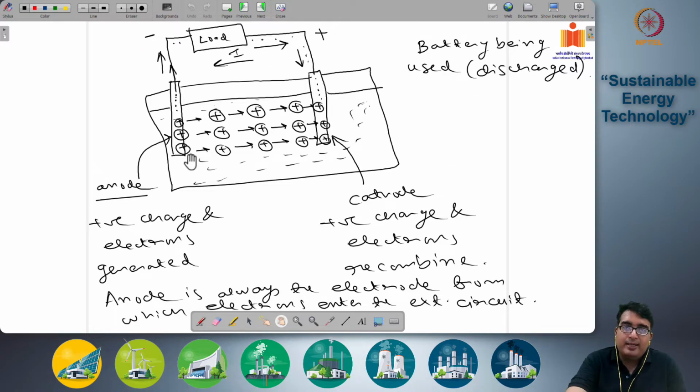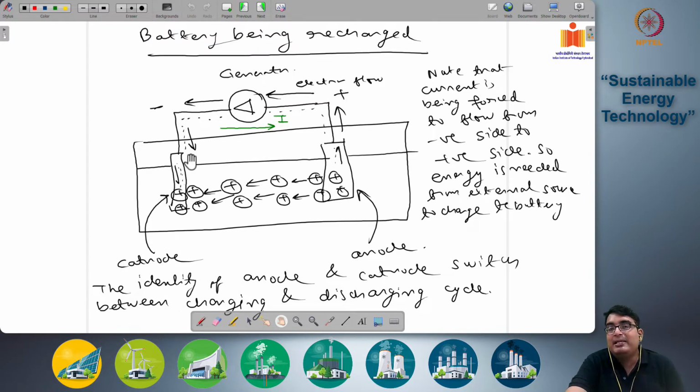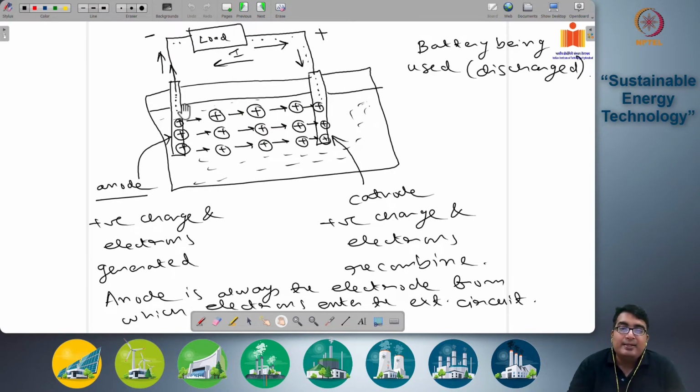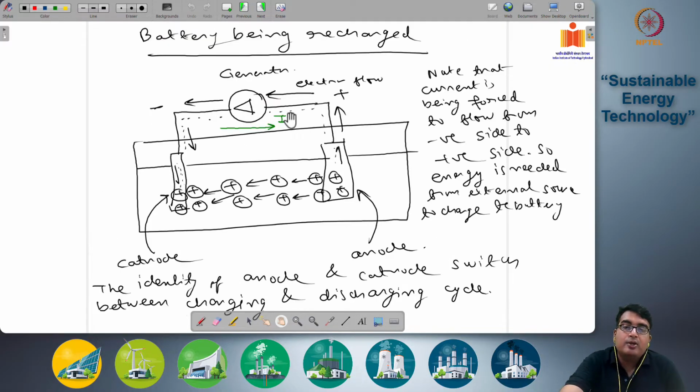So in a battery, energy is being given to the external circuit during the discharge process, and energy is being absorbed from the external circuit during the recharging process. So what this means is, the net energy difference between the energy released during the recombination reaction minus energy consumed during the dissociation reaction is positive during the discharge process, whereas the reverse is negative.